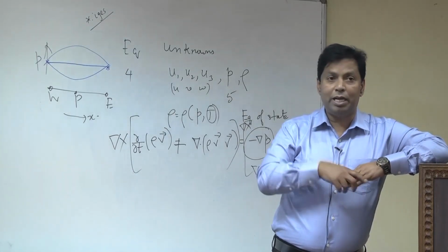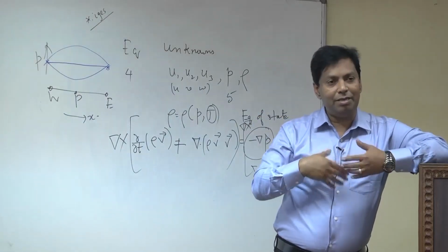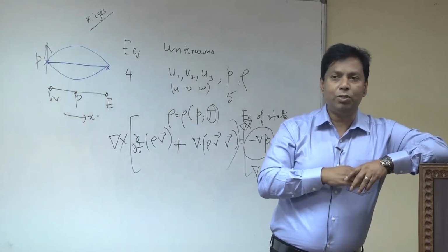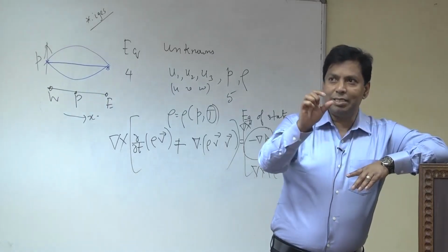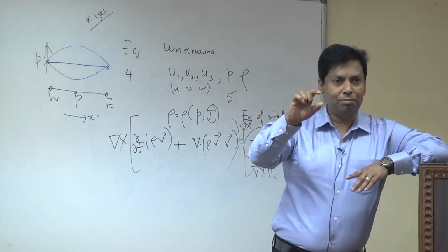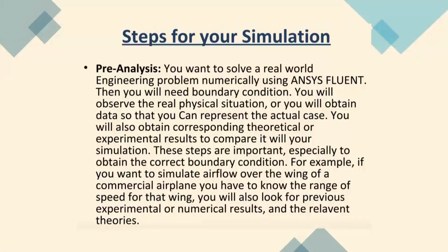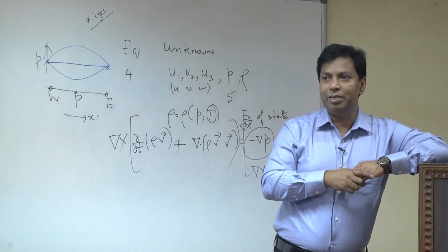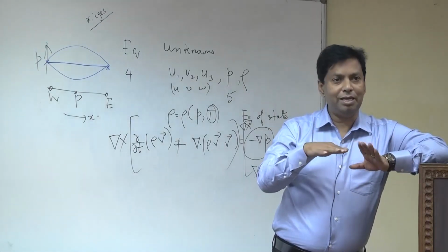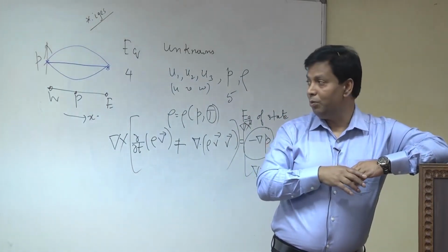Professor Chakraborty told that there is an upper limit and a lower limit of acceptance. Generally, as a CFD researcher, if we compare our result with some numerical results, we take an error of about 2% maximum. If the error is less than 2%, we accept. But if we compare our result with experimental data, we can accept up to 10 to 15% error, because, as I told, experiments have a lot of uncertainty, with influence from the environment. So we still accept it.